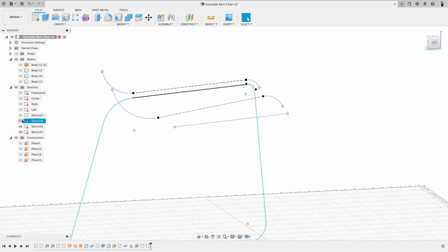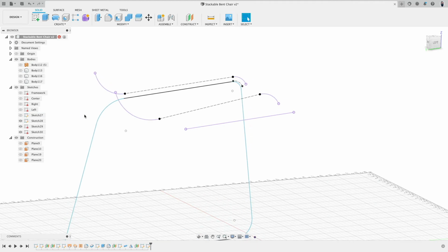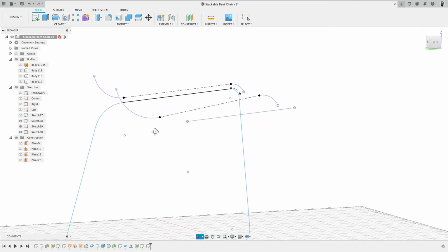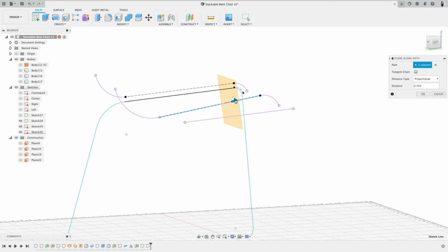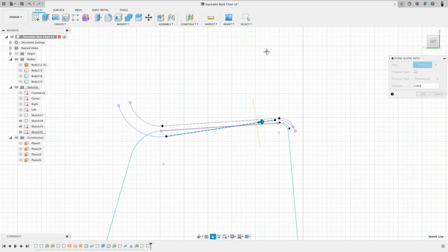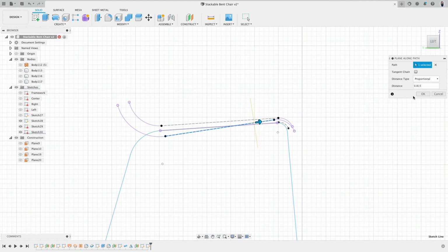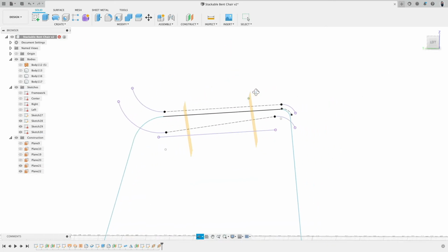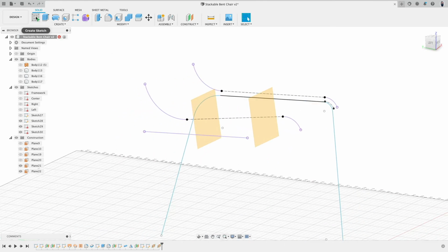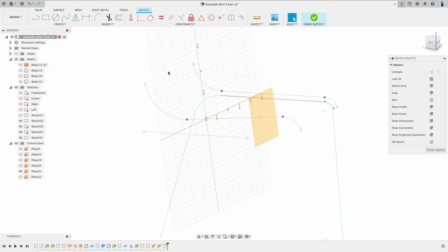Okay, now you might ask yourself, what's going on here? The next step is going to be actually very, very easy. Okay, so I will go ahead and create a construction plane. Chain off on this line. Maybe somewhere here at the front. Maybe at 80%. Then I go right click construction plane there and say this at 20%. Okay. Then let's maybe start with the back one. That's going to be more interesting.